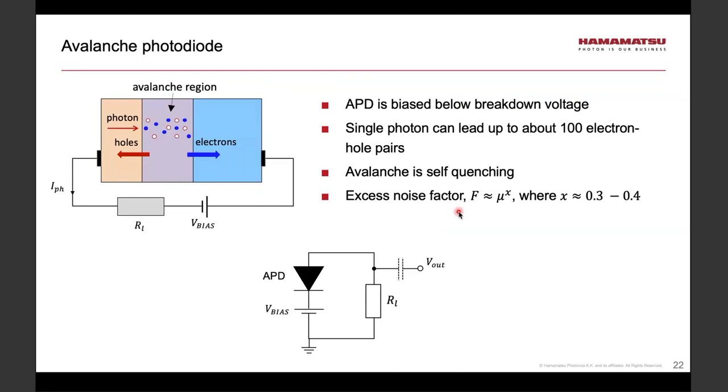I should have said earlier that in the case of a PMT, the excess noise actually diminishes with the gain. So there's the opposite behavior, and it's approximately given by the gain of the first dynode divided by that gain minus 1, approximately.